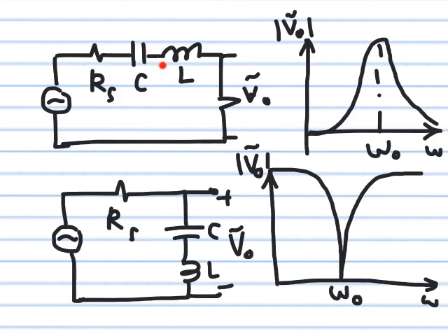Very simple. Because the impedance of the inductor is jωL. So when omega goes to infinity, jωL becomes very large. Effectively, at very high frequency, it's open circuit. So again, the link is cut between the output and the input. And again, the output will go to zero. What about at resonance? At resonance, you get maximum current going through. When I say maximum current, I mean the current with maximum amplitude. Then the amplitude of V output will be maximum.